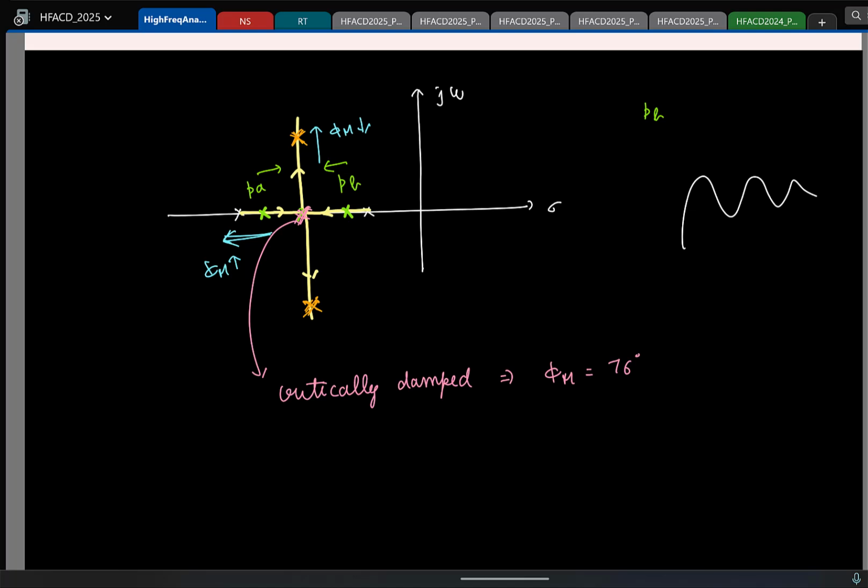Okay. So this is one condition to aim for, but you can also have other constraints imposed based on the closed loop response. Let us say the closed loop transfer function is 1 by beta times the loop gain by 1 plus loop gain. And let us say I have a first order system. What is the phase margin?